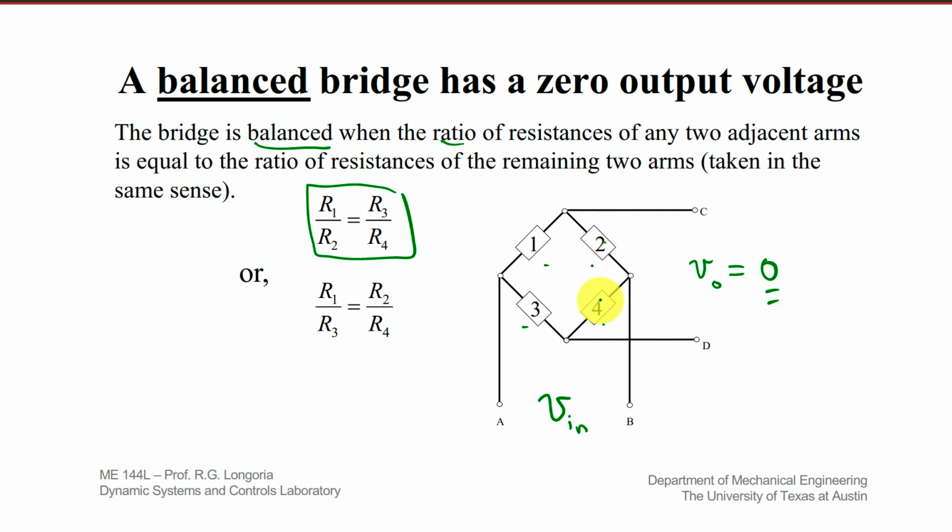So imagine now these are strain gauges, and usually in a Wheatstone bridge with strain gauges, all these would be the same, right? So if any one of these changes slightly, right, there's a little delta R, say, due to a strain of this resistive strain gauge, then this output is going to change from 0, right? It won't be equal to 0. That will be an unbalanced bridge. So that's how we basically detect changes in resistance, through this bridge.